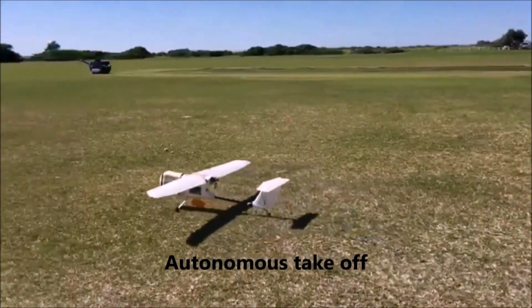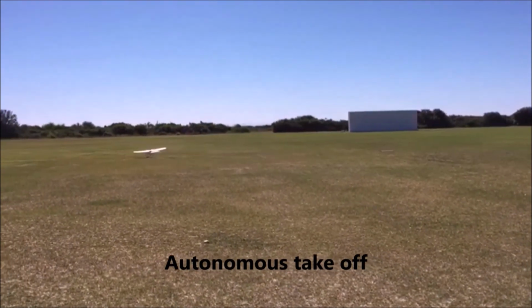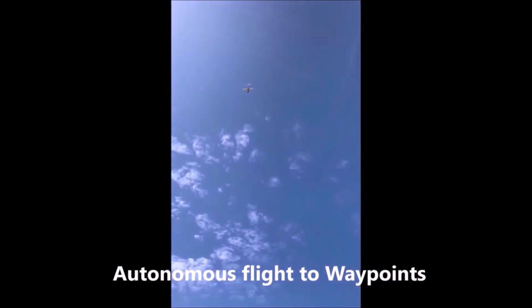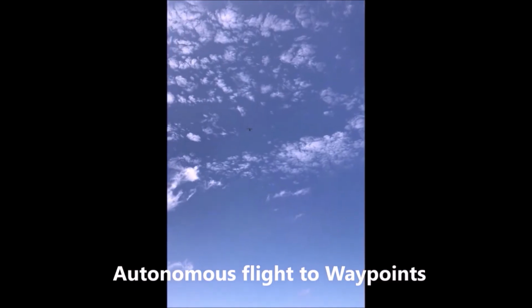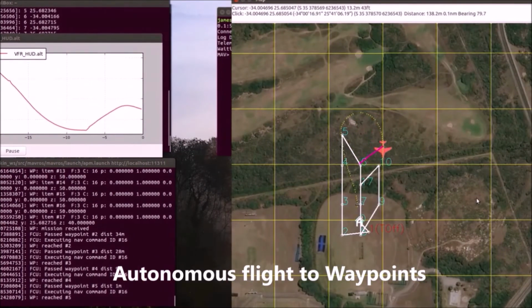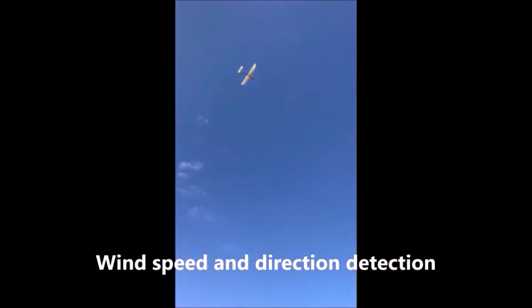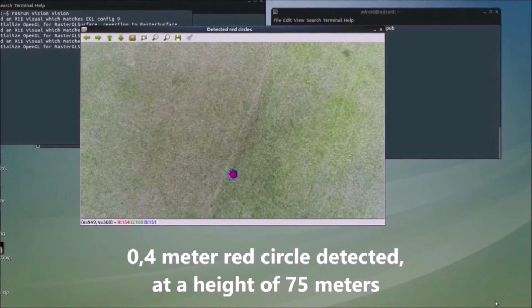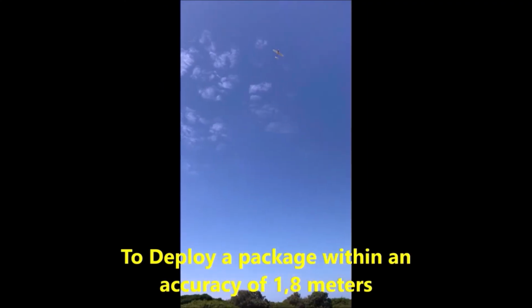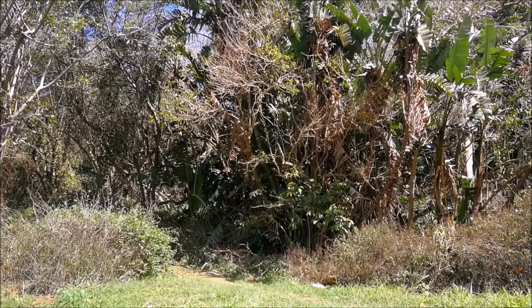Then the autonomous flight and packaging delivery system was made so that we can deliver packages like medical supplies in a deserted area. It's able to take off automatically and fly to different waypoints as well. It's able to detect the wind speed and the direction, and then from this be able to deploy a package on a red circle that's 0.4 meters in diameter at a height of 75 meters above the ground.